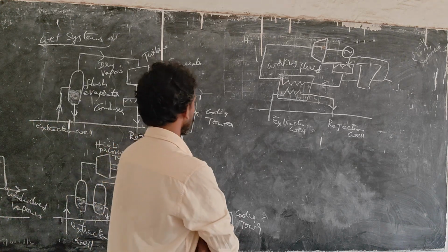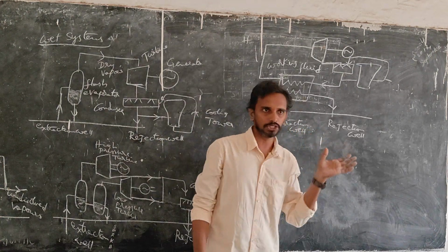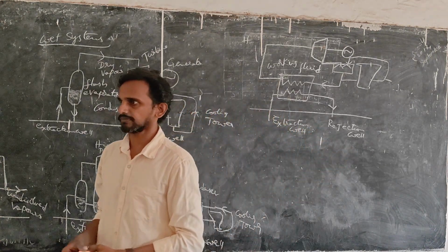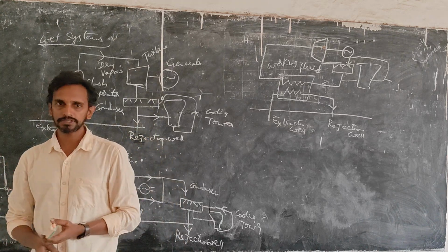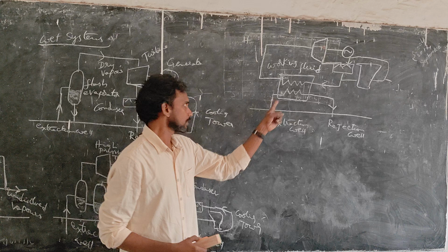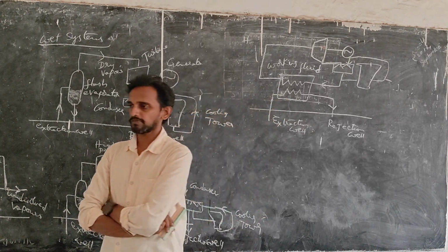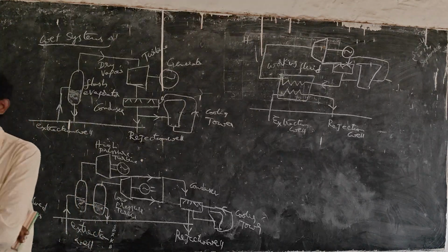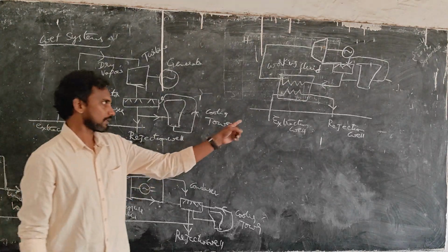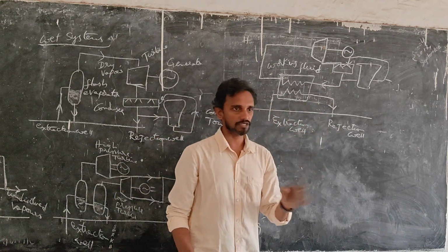So when you have very high contaminants and damaging, corrosive materials from geothermal resources, then we use a heat exchanger. So there will be a working fluid which runs through the turbine, and all the geological fluids will be sent back to earth after collecting heat.